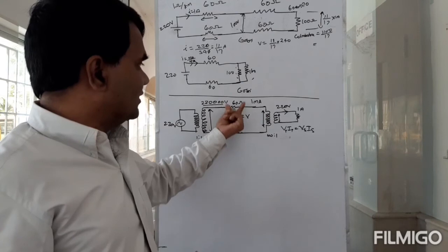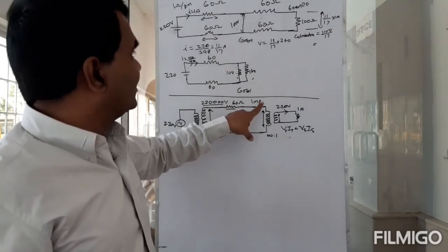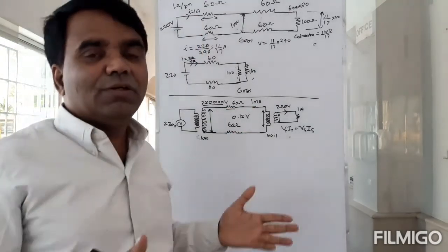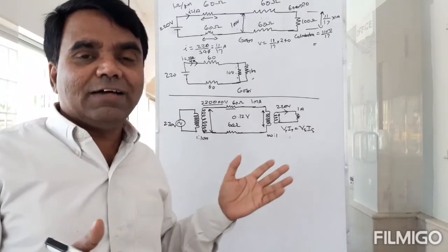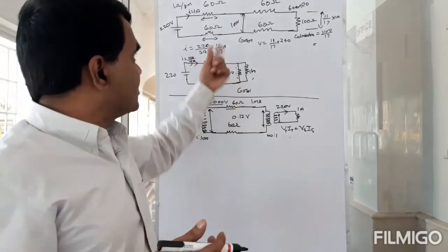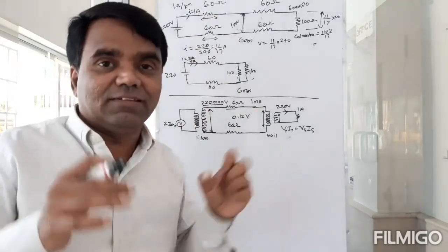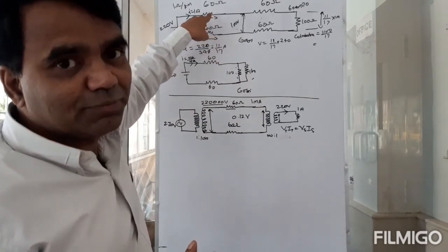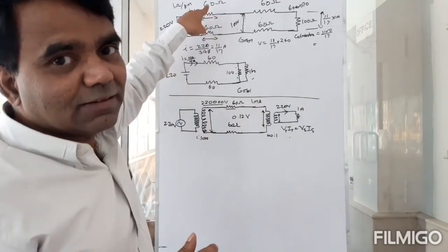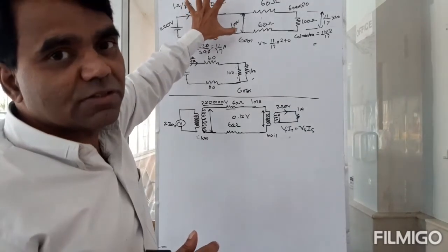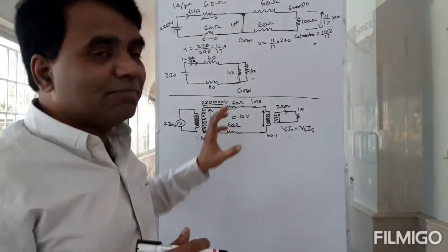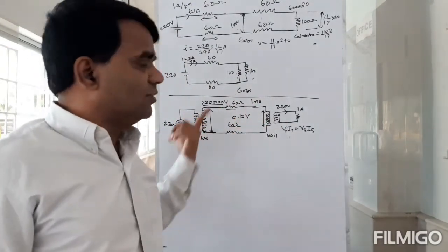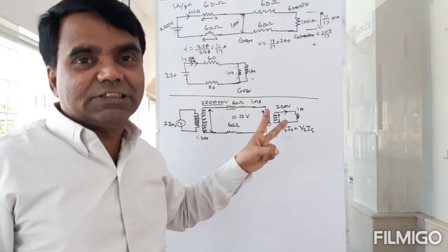And the power loss, you see, is much less. I have only 1 milliampere. Previously 1 ampere was flowing through it. Now it's only 1 milliampere. So I squared R, I would have reduced the power loss by 1 million. The power loss here is only 1 millionth of what the power loss was happening here. If 1 million watts was dissipated here, I am dissipating only 1 watt. You see what a drastic change. So by using transformers, I can have these two advantages.